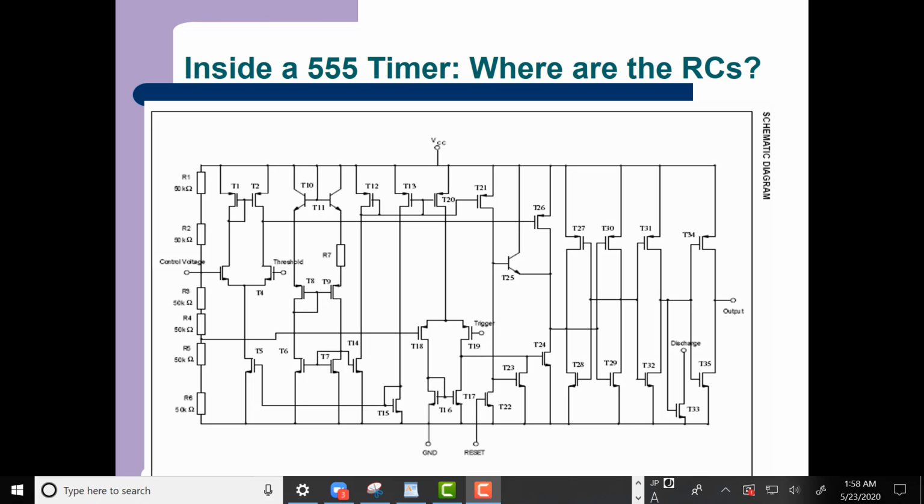If you look at a circuit like this, it looks like an extremely complicated circuit. This is a 555 timer, so it has a couple of things that you won't see in analog circuits. For example, you've got inverters over here. You've got cross-coupled inverters, and remember, a cross-coupled inverter is a memory cell. And those that have done 555 timers, you know there's an RS latch. So this is probably part of the RS latch over here. But yeah, this is a really complicated circuit. And you say, oh my goodness, where do I start?